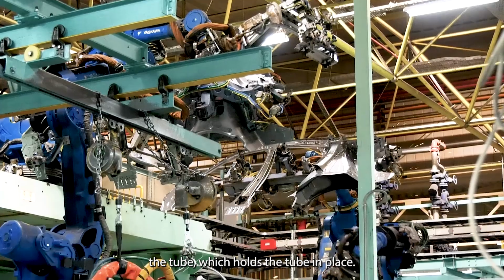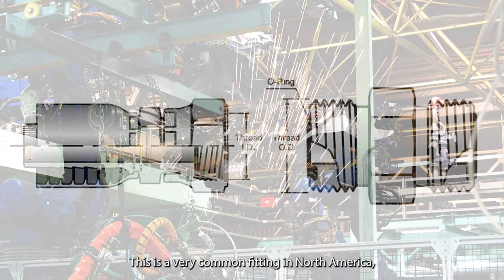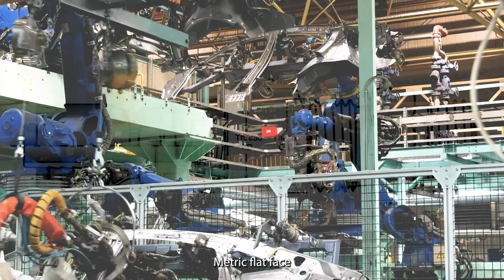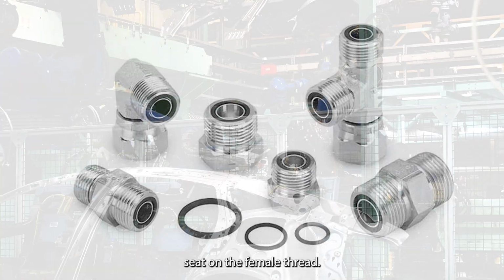place. O-ring face seal fittings. O-ring face seal. This is a very common fitting in North America known as O-ring face seal, ORFS, but is also used with British threads, HIAB, as well as metric threads, metric flat face. Essentially, face seal fittings seal between an O-ring located in the face of the straight male thread and the flat face seat on the female thread.